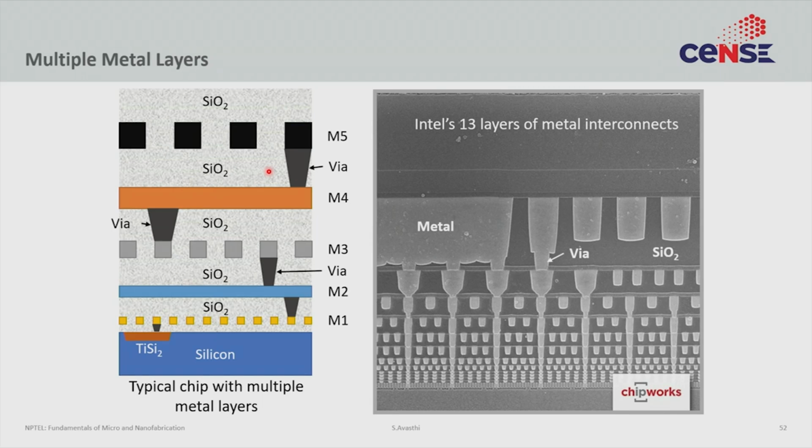You see, all of this silicon dioxide is being deposited on top of these metal layers. And if there is one thing we have learnt in the diffusion lecture, it is that metals diffuse very fast. So once you have deposited a metal, you can never take the wafer to high temperatures, which means all these deposited silicon dioxides must also be deposited at lower temperatures, low enough so that the metal does not diffuse. So all of these silicon dioxides tend to be low temperature deposited oxides, and low temperature deposited oxides tend to have poorer properties, and that is something we have to deal with.